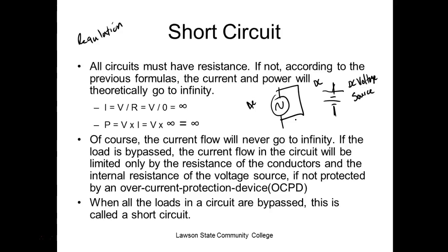Now what happens on a regulated voltage source is this wire starts getting really hot. And what happens to its R? It goes up. Well, now we've got a higher R, so what's your regulator going to do? It's going to raise this voltage up a little more. It's trying to shoot for the maximum output.